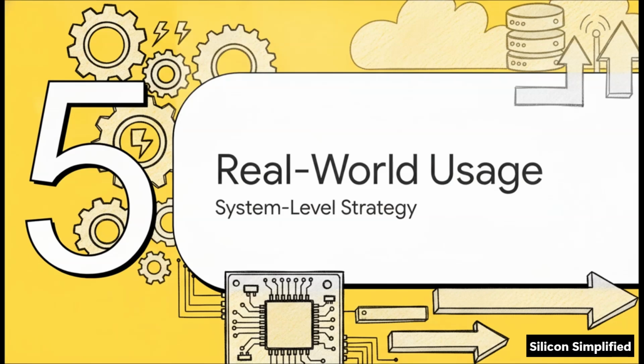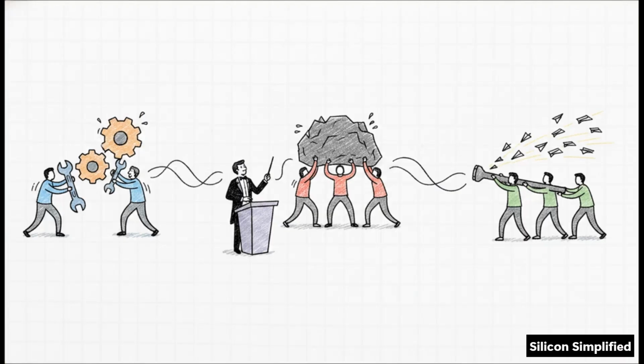How do we actually take these building blocks to the system level? Out in the wild, verification engineers use these exact mechanics to wrap up insanely complex operations, like entire network protocol stacks, into single reusable objects. Imagine bringing up a complex SoC. You might have several sequences running totally independently, all managed by a master virtual sequence. A virtual sequence is incredibly powerful because it controls multiple other sequencers without being tied to a specific hardware interface itself. It acts as the ultimate system-level orchestrator.